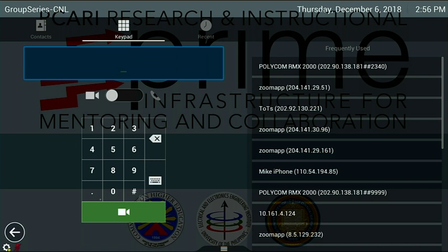So let me ask you, can I use this op amp in a unity gain? Are we going to play penguins again? You say no? How many people say yes? How many people say no? It would not have phase margin if I closed that unity gain. I've tortured you enough. Let's just do it.